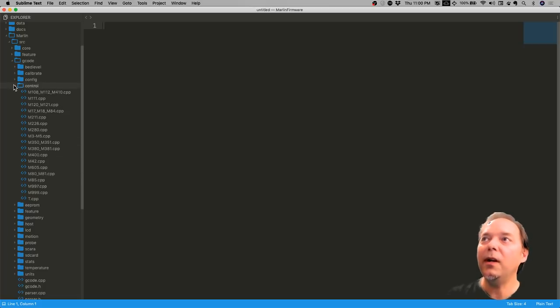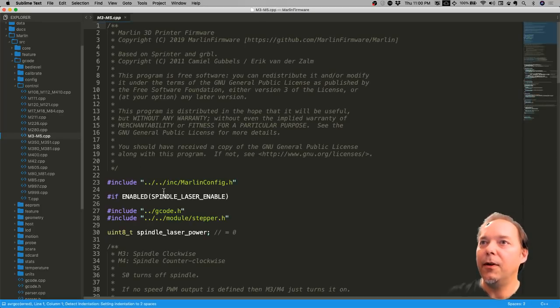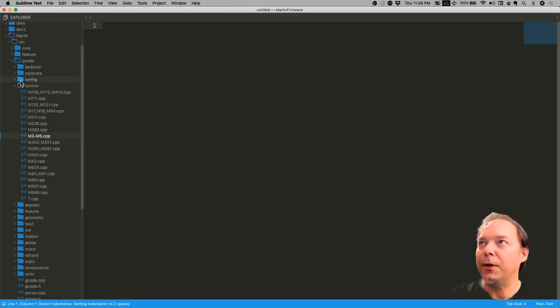Yeah, control. Again, similar to config, but these are like setting things like turning a device on or off. A laser or a spindle, for example, turning it on and off. So I won't go over all these commands, but you can look through this. And tool change is also included here, interestingly. Recovering from a hard stop, M999. M108, M112, and M410 are grouped. But those are also with the emergency parser, so that's probably why. Again, there was a reason why I grouped them together.